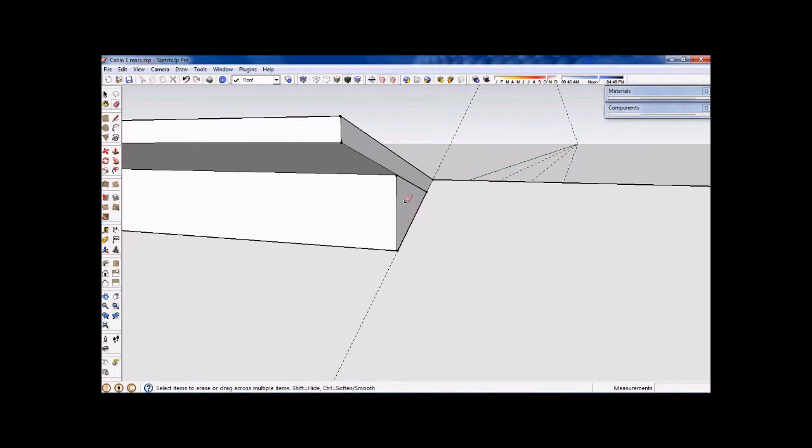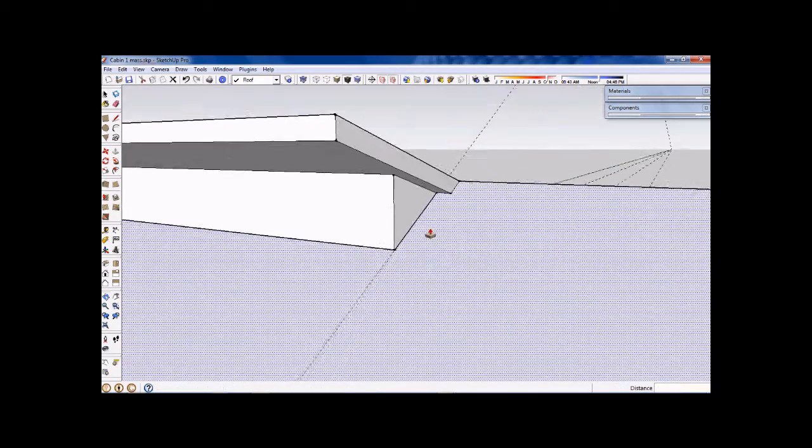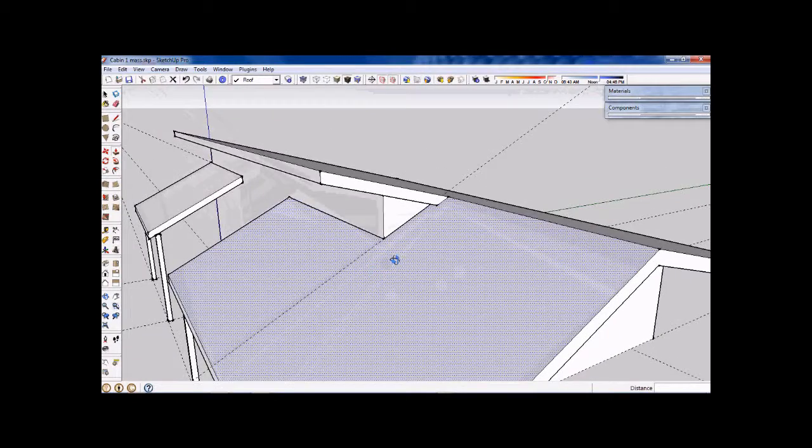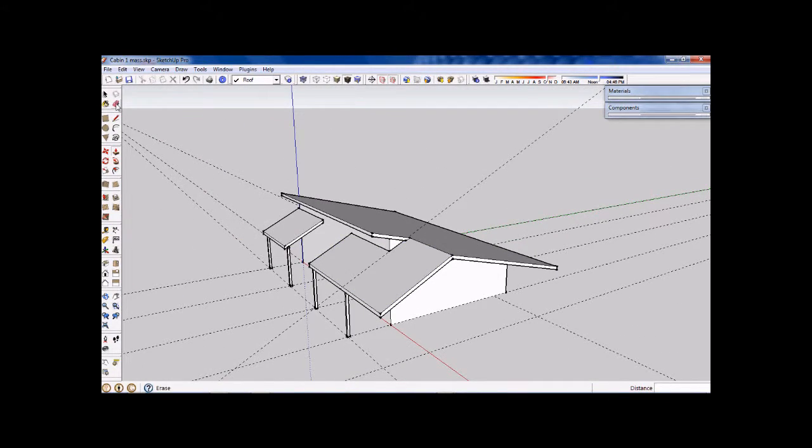So if I grab my push-pull tool and push-pull this surface here out another 140, so I'm letting go and typing 140 and pressing enter, that would give me a total of a 150mm overhang on that roof edge there. And I've just got to pick up my eraser again to get rid of that construction line, and that's looking fairly tidy at this